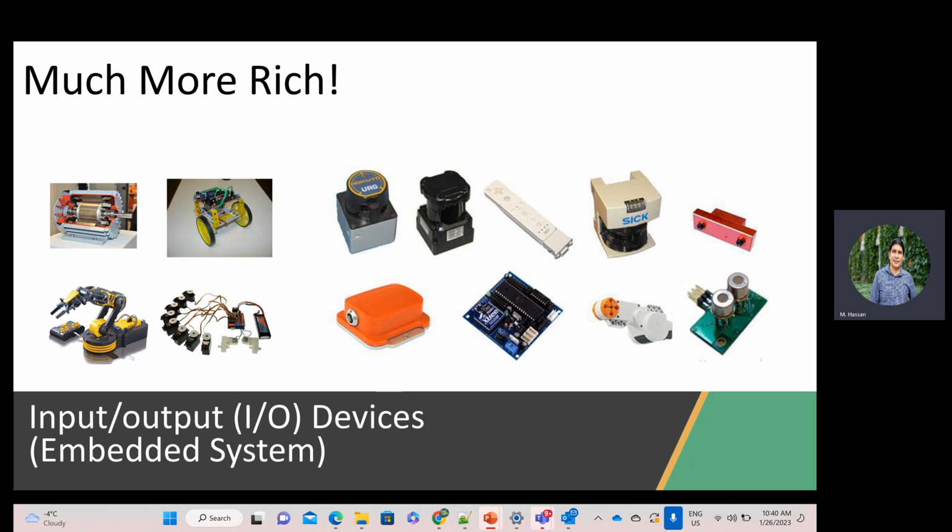This usually also happens through IO devices like motors, for example, as you see in lab 1, right? So in lab 1, what you will do is read data from the IMU, from the gyroscope, for example. So this is the sensor, but this sensor is interfaced through an IO protocol that in a couple of slides we'll discuss. And then when you actuate, when you change the speed of the motor, then you also need to write into an IO device.